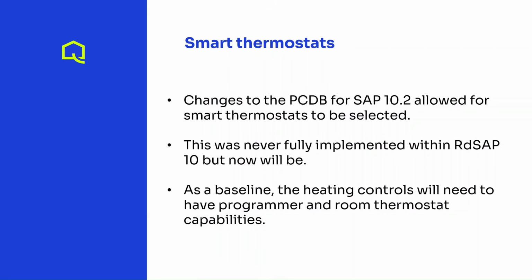The selection of smart thermostats is based on the level of control already within the dwelling. At a minimum, the heating controls should have the ability to program different heating periods as well as having a room thermostat. Smart thermostats should already be input as a programmer and room thermostat.